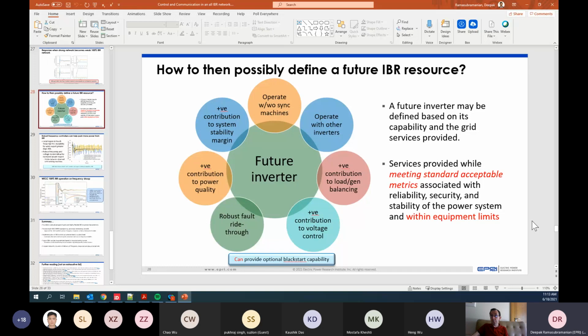grid forming? How do we conceptually educate on what is grid forming, what is grid following? That's something that we've been working on, especially through ESIG and through IEEE, looking at the fact that the voltage phasor is constant in the subtransient time frame, or you don't allow the voltage to change in the subtransient time frame, but allow the current to change in the subtransient to transient time frame. So there, you can have a type of conceptual definition.